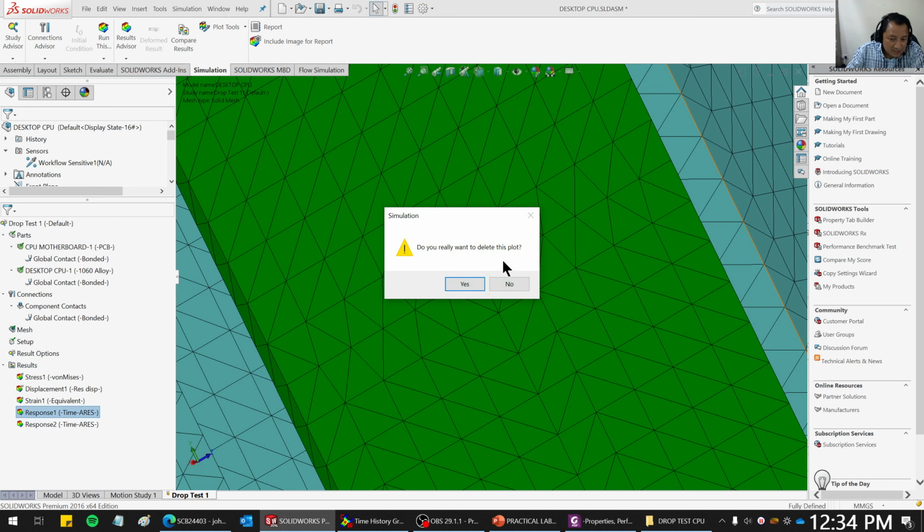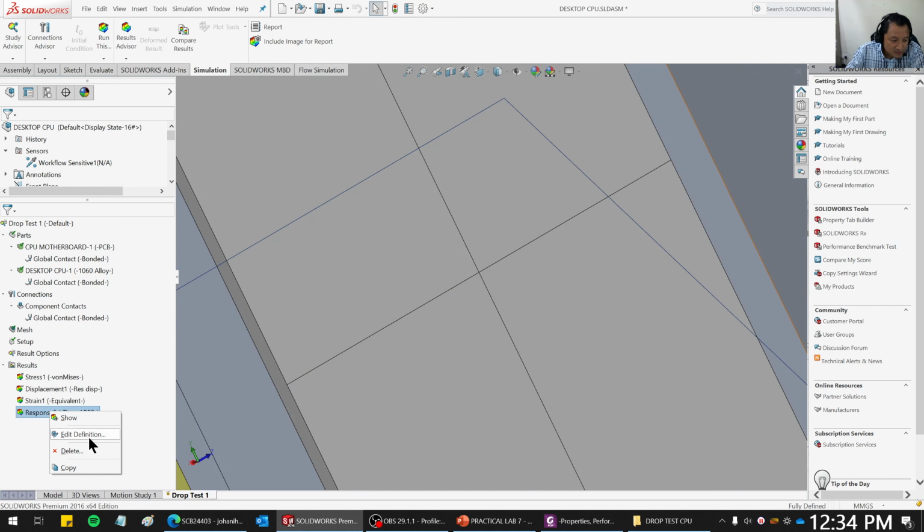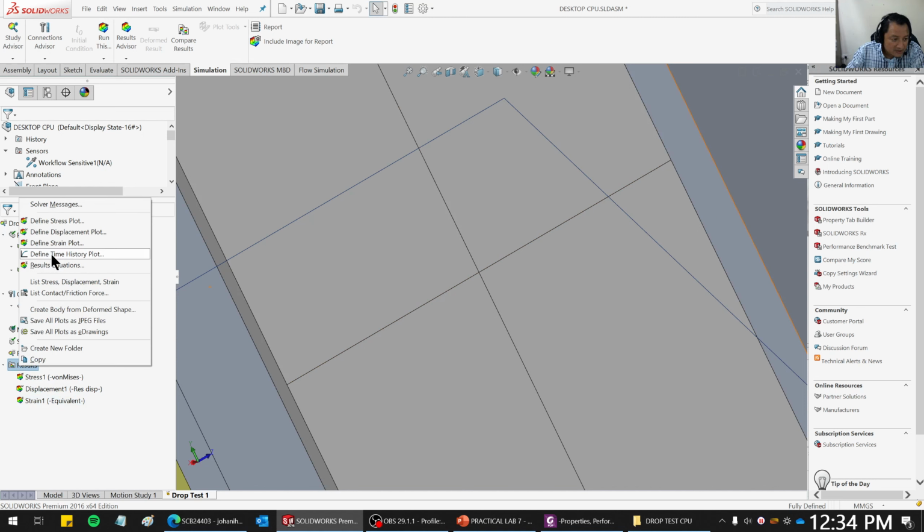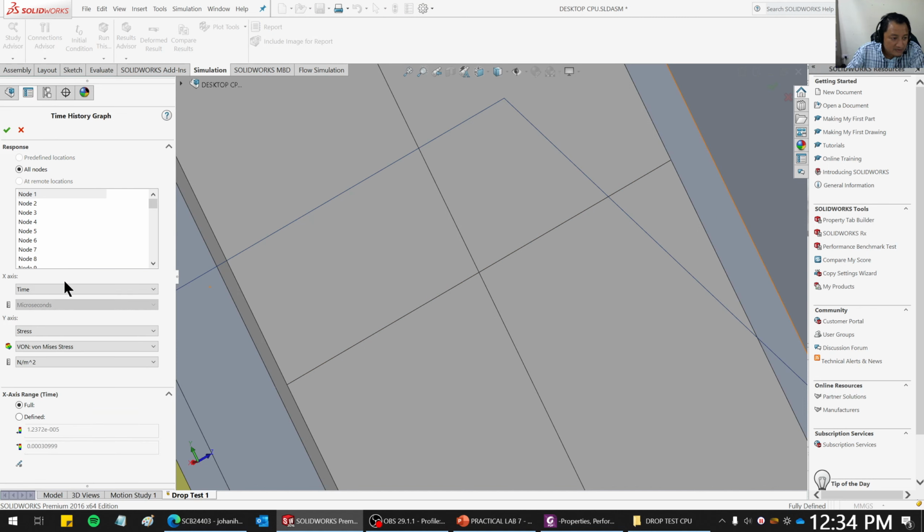Response time, delete. Yes. Response to, delete. Yes. Result, define time history plot. Node 69. Time, change to translation, acceleration.